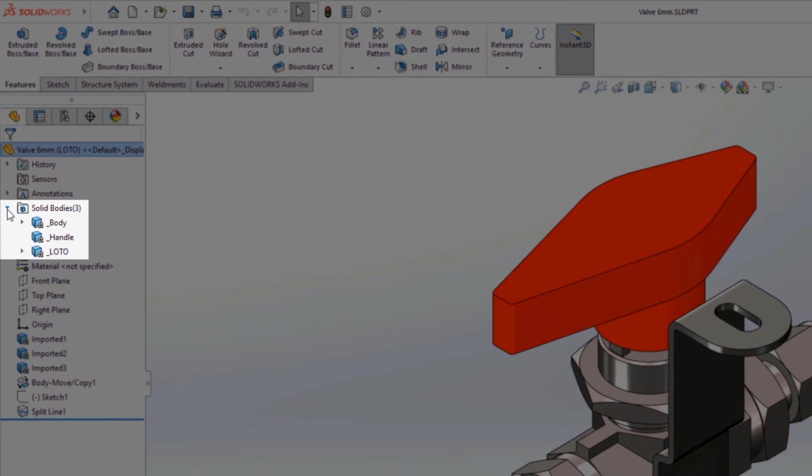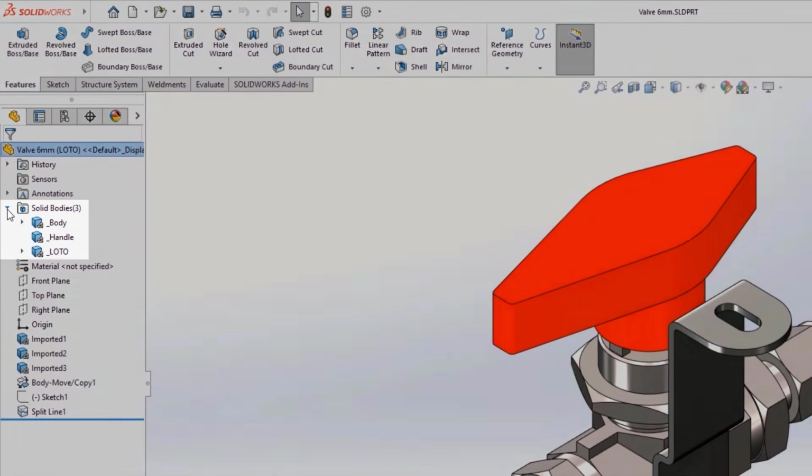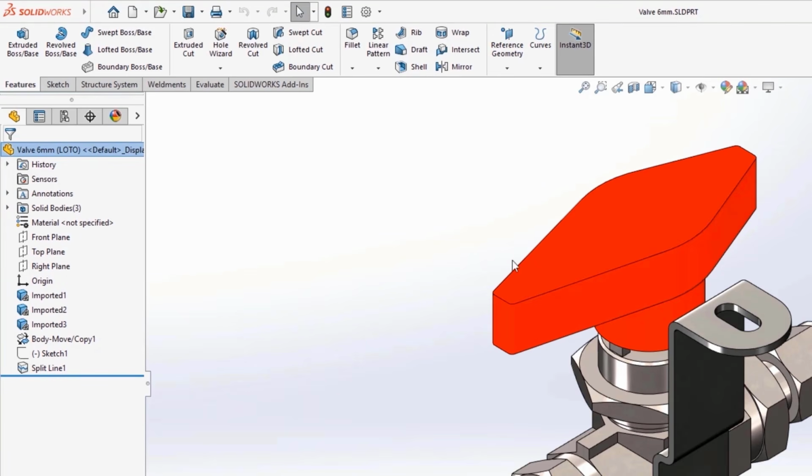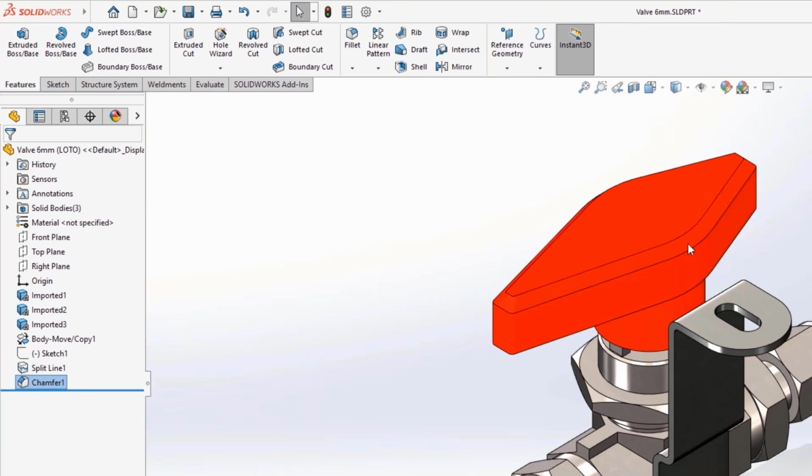But now in many cases inside of SOLIDWORKS Design, you can now apply familiar tools like cuts, chamfers, fillets directly on mesh bodies. Now, some of these features, you're probably thinking I would only traditionally do these on solid bodies, but that's not necessarily the case today. So you think about that bridge from having that scan data, having that neutral file data, and then bringing it into SOLIDWORKS Design. That bridge to an editable design, in a lot of ways, kind of got built.